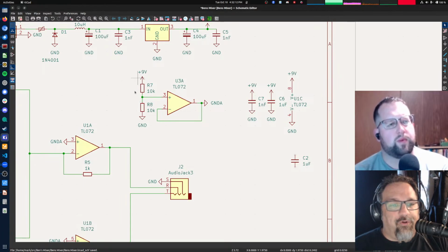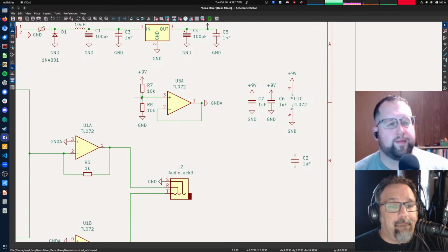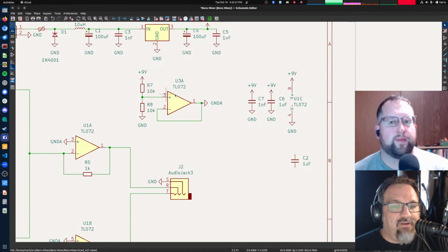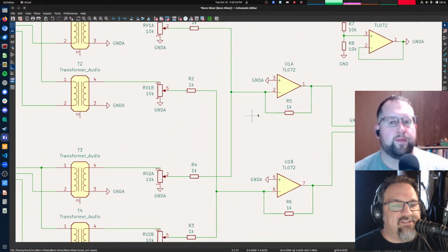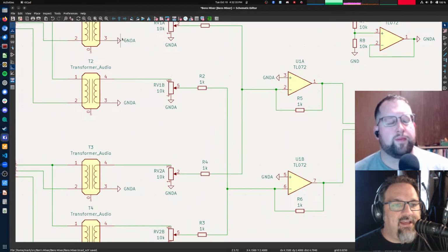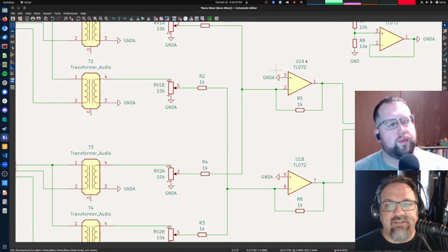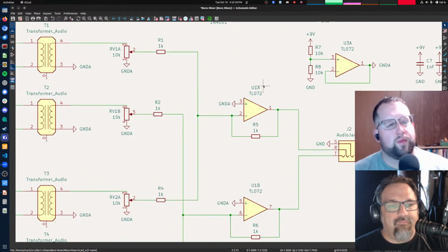Okay. So the voltage divider here generates the voltage, but it's a high impedance. And so we feed that high impedance into the op amp in a voltage follower mode, and that lowers the impedance. It's the same voltage on the output, but it's a much lower impedance. And that lower impedance will now drive all of these places that we are using that voltage. Analog ground, all over the place. Okay?